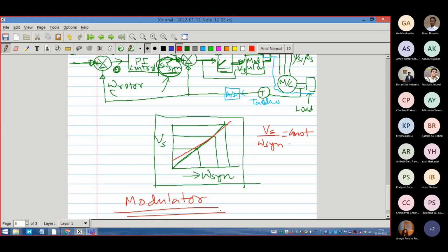But we say that this is a different subject where you need to know the system's poles and zeros. You have to write differential equations, which probably you have learned how to do for a system, and then find out the system transfer function, and then you can design a PI control. This is H(s). The rest of the thing is G(s), the system transfer function.